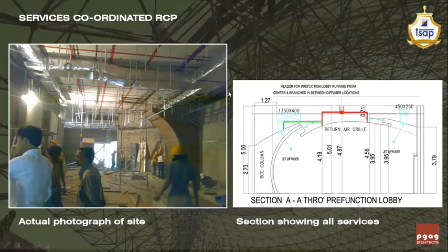Now you can correlate this particular section with the as-per-site conditions, how the ducts have been laid and how the sprinkler pipes have been laid. The contractor is also supposed to give the final finish false ceiling line out to the services contractor as well. In some corner of the site, he is supposed to give the line out for the services contractor also to be aware of what is going to be the final finished height of the gypsum false ceiling,